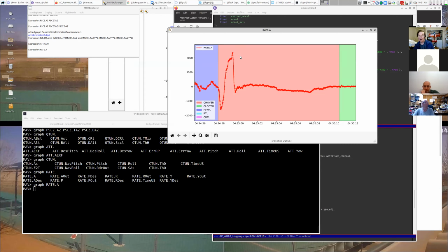All right, so that was 2 bugs. I love logs where we actually find bugs and then we can get them fixed. It's partly why it's often worth looking a bit further than just the issue that the pilot raises, because we often find new things. Like, for example, I hadn't even noticed the first time I looked at this log that the innovations on the true airspeed were 0, meaning it wasn't fusing airspeed. And so that's a bug we haven't actually got fixed yet.